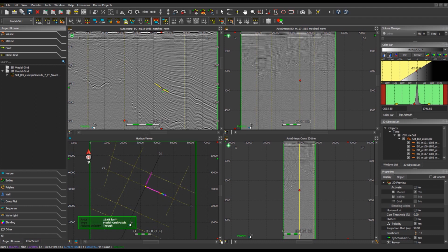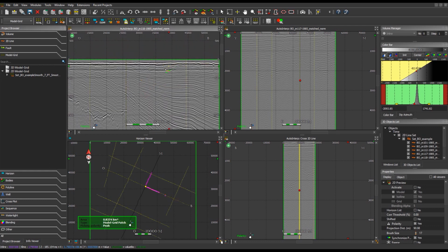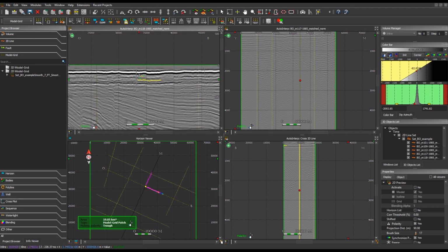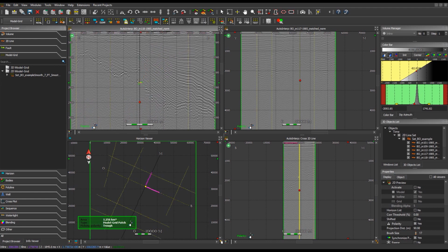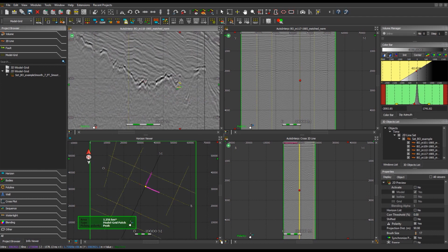At least two horizons must be interpreted, one at the top and one at the bottom, so as to create the geomodel between the horizons. Although various methods are possible, we recommend to interpret one line at a time. Once a horizon has been interpreted, click on the Mark button or press M to validate the interpretation. The edited horizon will appear on the seismic with a specific color.